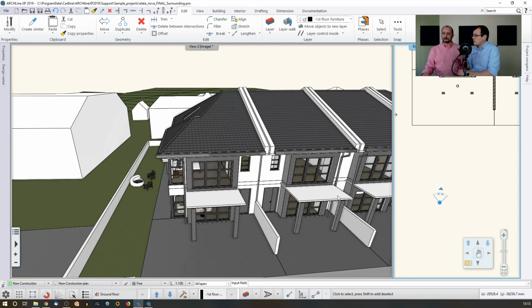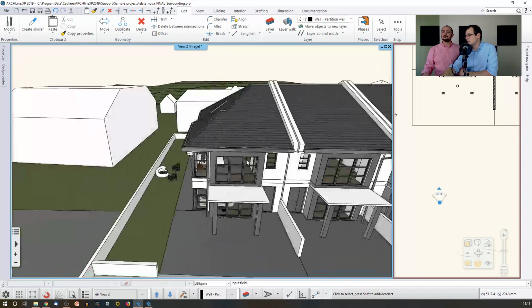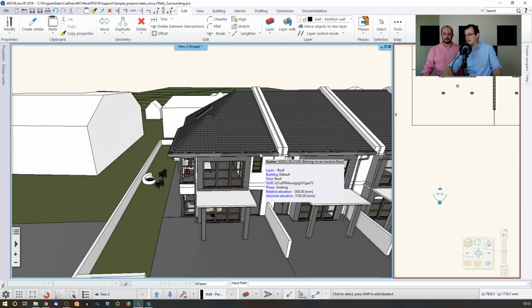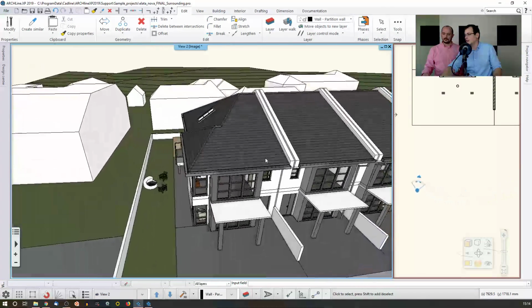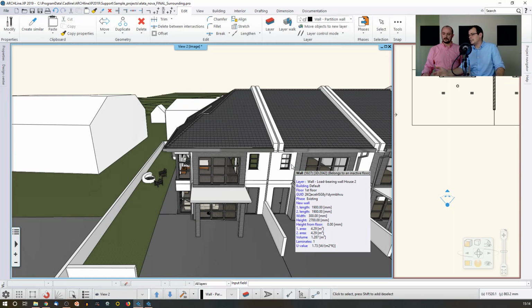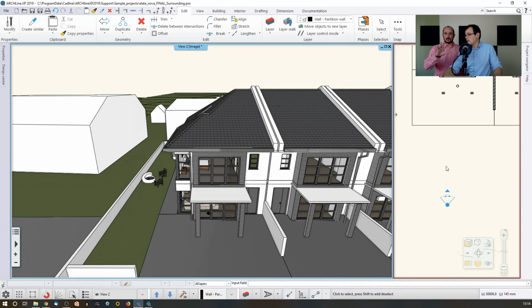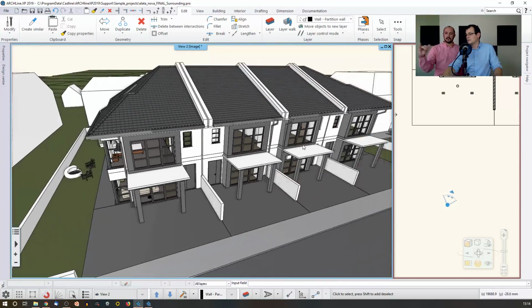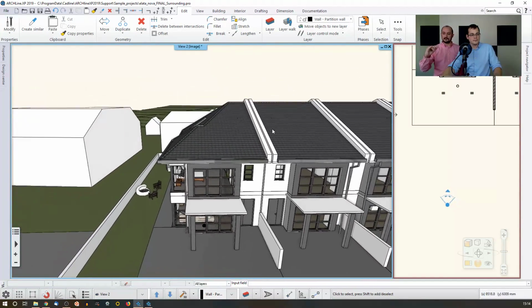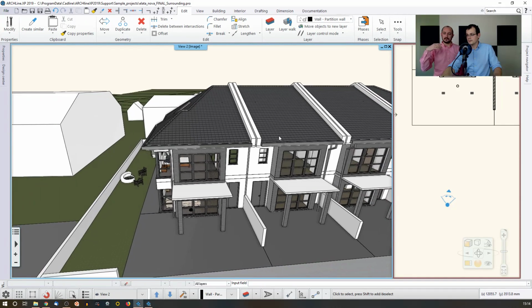Or another scenario, maybe you want to show your clients around. Obviously, there are navigational tools, so you could use the shift and the mouse wheel combination to look around, but that's not that easy. Oh, that was the right click. If you just keep holding the right mouse button, you can look around. So that's different from Orbit. That's a look around tool.